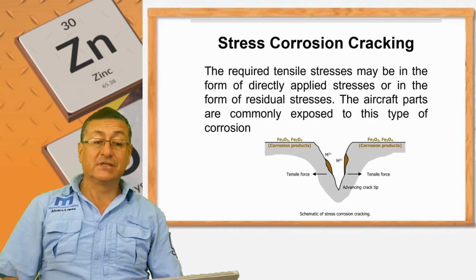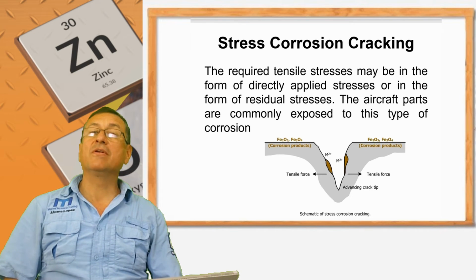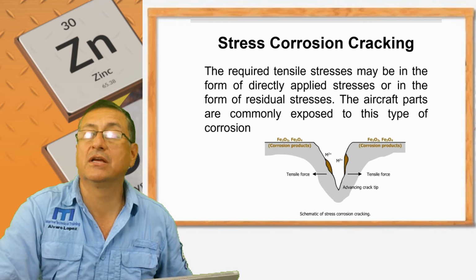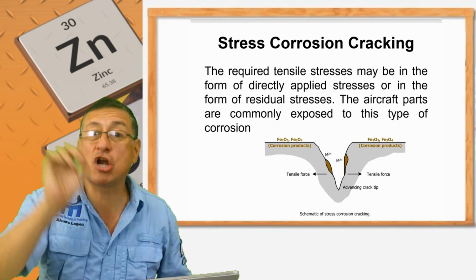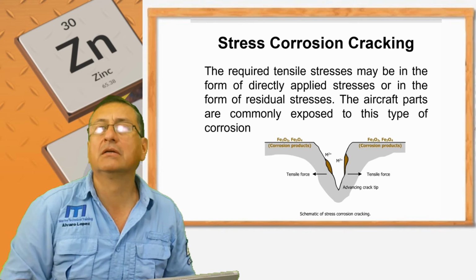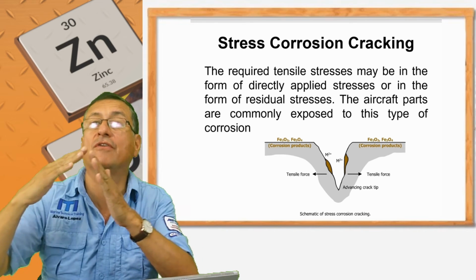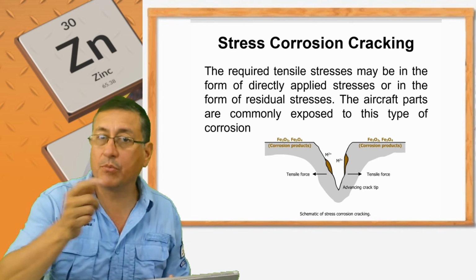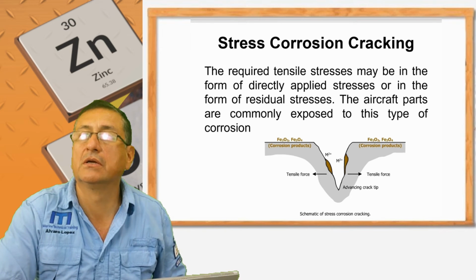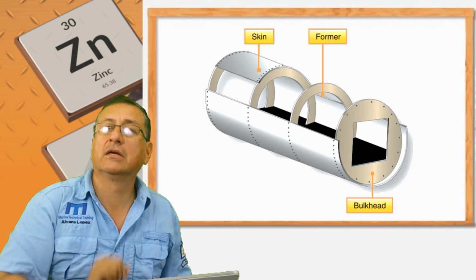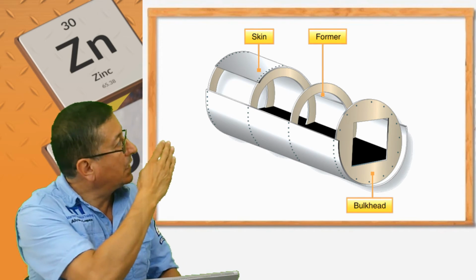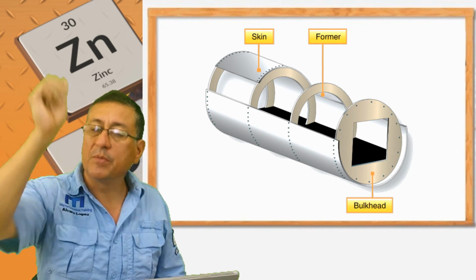In aircraft, it is very common. For that reason, in aircraft, one of the rules is no corners. Everything is rounded to avoid concentration of stress in those corners. For example, the windows on the airplanes. Some years ago, the windows were square, and they discovered that on those corners, the crack is propagated.